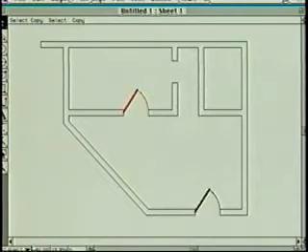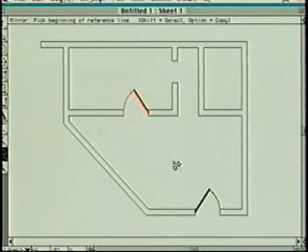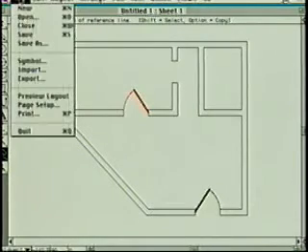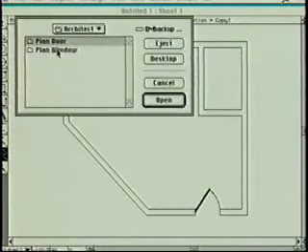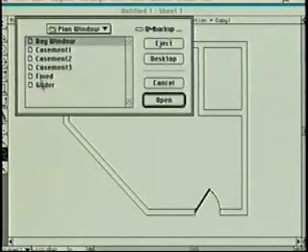And then with my mirror tool, I could take this and say, well, let's put the hinge on the other side. And it flips it over. Let's put a window in. I can go to my symbol menu, and let's get out of the doors and go into the windows. We've got doors, windows. The architectural ones, we mostly provided doors and windows. We find that people want to create their own for most of their other usages.